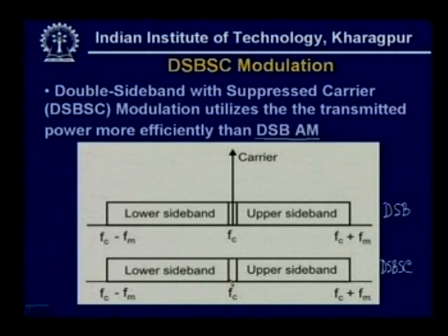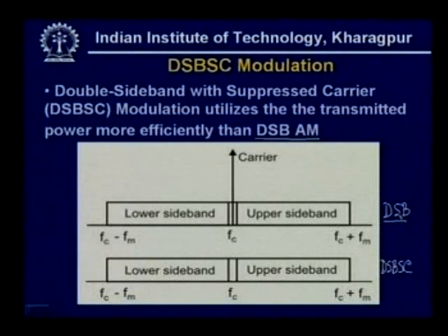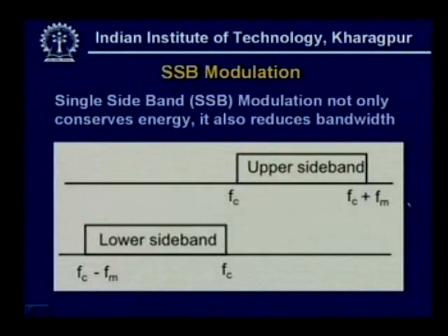We see the carrier is not present. To transmit this signal will require less than half the power than is possible by using double sideband transmission. This is the primary advantage of the DSB-SC modulation. However, it has some disadvantage in recovering the signal that we shall discuss later.